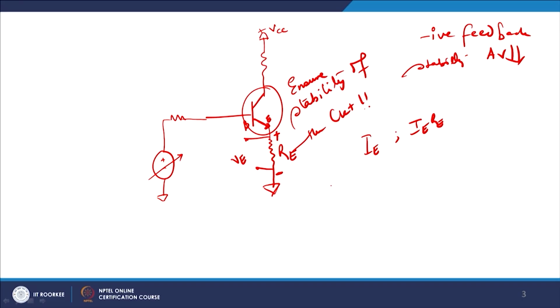As it starts to reverse bias it, why? Because you are applying the positive side to the N type and the negative side to the P type, or even a positive bias to the N side. As a result, the emitter is getting more and more positive, which means it is trying to reverse bias the emitter base junction, and therefore the majority current carrier is reducing and a large amount of minority current carrier appears. Therefore, when you apply Re, your gain starts to fall down, and it keeps going down.